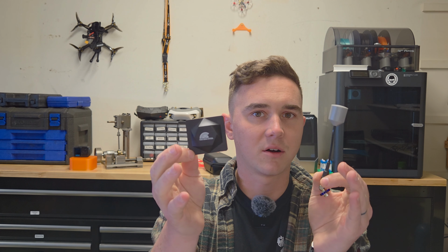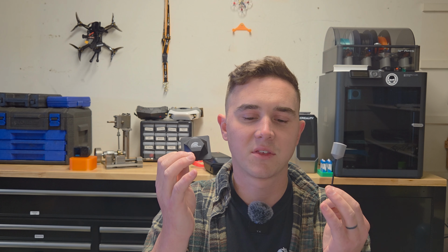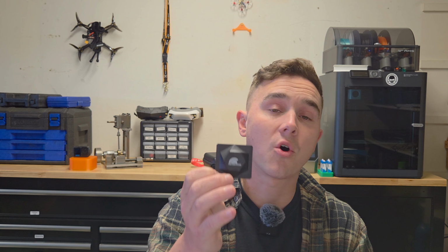That's pretty much how it's broadcasting. The omnidirectional broadcasts everywhere in a giant circle. It looks a little bit different than that, but generally speaking, a big sphere. And this looks more like a cone. This has degrees, this doesn't. Each one of these has something called gain, which is basically its sensitivity. These are going to be higher gain, which means they're going to be more sensitive when receiving a signal. But it's harder for them to receive a signal if they're not facing that direction. This is going to be less gain, so less sensitive, but it's going to be able to receive from pretty much any direction.